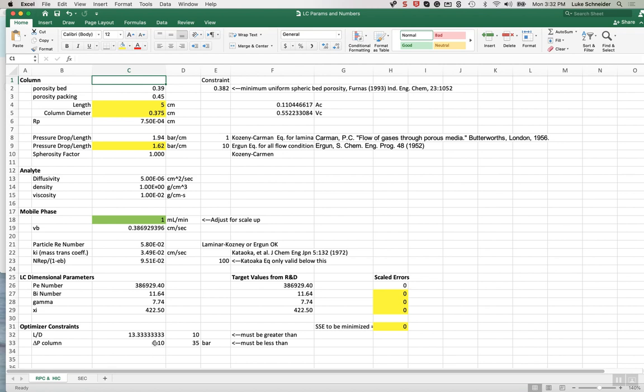The pressure drop through the column is always a concern. Because we've packed the column with small beads, no matter how big that cross section is, at some point we just can't pump things through. We have a limit on the pump, or a limit on the materials of construction of the column. Laboratory scale is easy to deal with because you can go with really thick, heavy metal columns. But in a plant setting, the diameters are so big that if you try a big pressure drop through a column, you'll just burst the column, and it doesn't work.